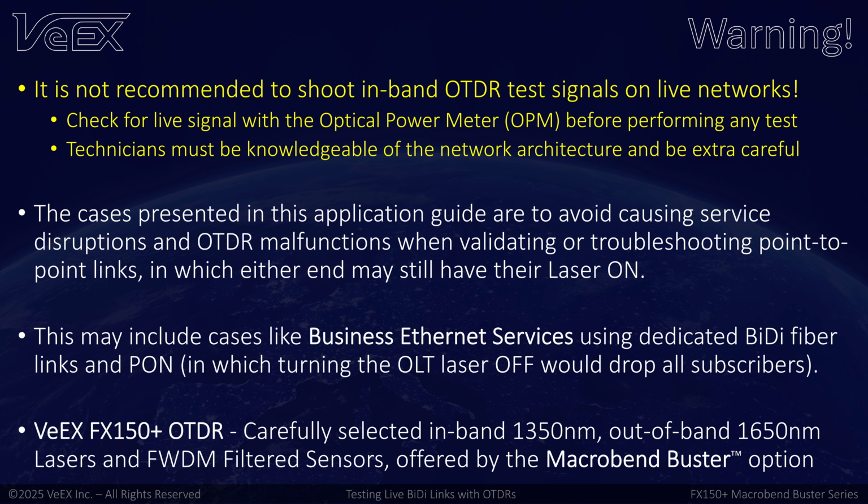In those cases, we recommend using the VeEX FX150 Plus OTDR with the Macrobend Buster option, which offers carefully selected in-band 1350 nanometer and out-of-band 1650 nanometer lasers, along with FWDM filtered sensors. This allows the OTDR to work even in the presence of common BiDi and PON wavelengths.